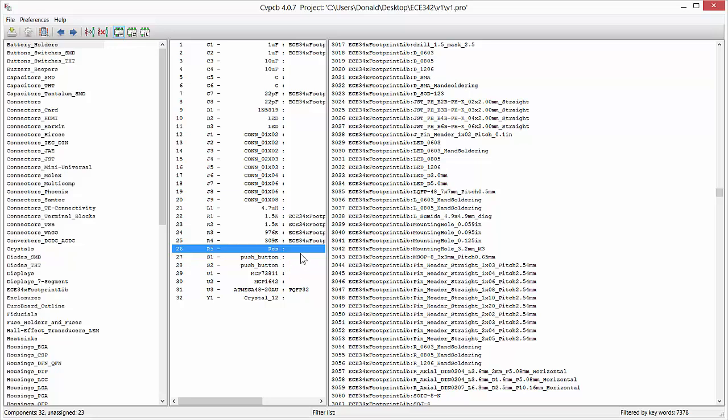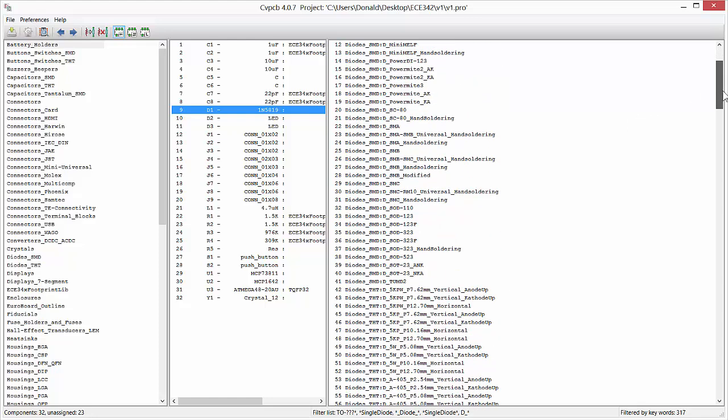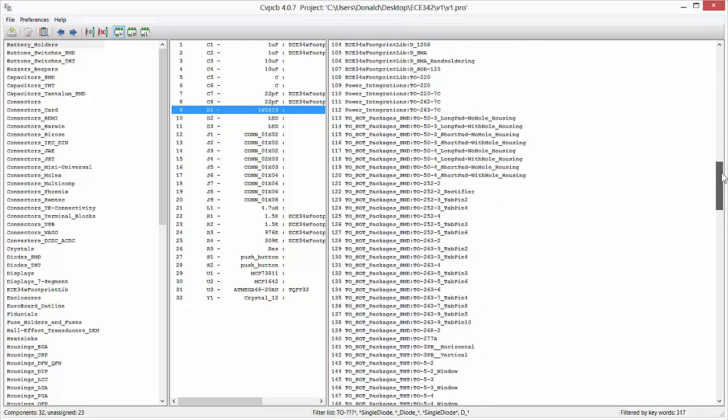All right. My push buttons, I have to go find geometries for those. They haven't been made yet, and that'll actually be part of what we're going to do in this little tutorial. In fact, we'll probably actually make all 4 of these parts before we're all said and done. The 1N5819, I haven't really chosen what package to do here. We do have a lot of surface mount packages, 0603s, 0805s, a lot of SMAs, a lot of these that are available for us in the standard libraries.